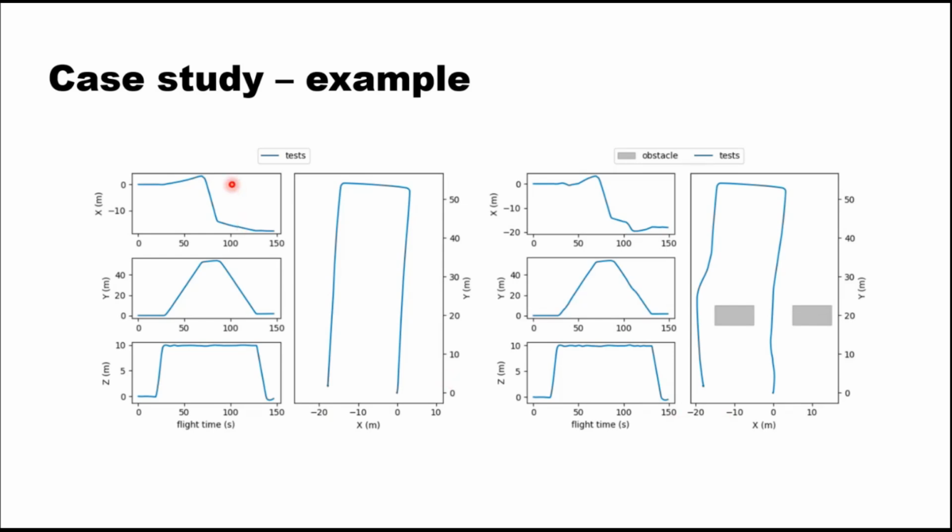Each test case or test suite is being developed for a case study. In this case, a case study is a mission, a flying mission. You have a starting point, waypoints, and the end point, the goal point. What we do is we take this file that defines the mission, and then we place obstacles by defining their position, dimension, and orientation, and then we run a simulation to see how good that test case was.